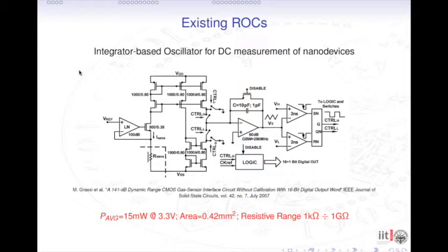On the contrary, compared to a traditional approach, where you measure a current, amplify that current and convert the current into a voltage signal, this readout circuit is based on the conversion of the nanosensor current into the time domain, designing a quasi-digital converter.